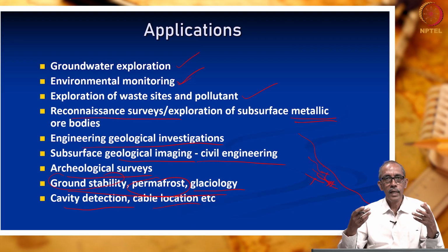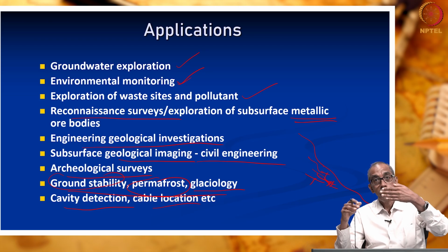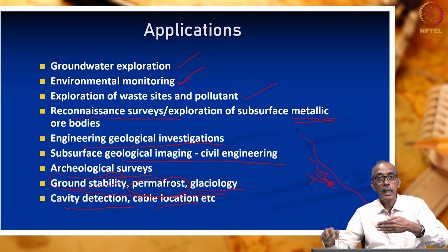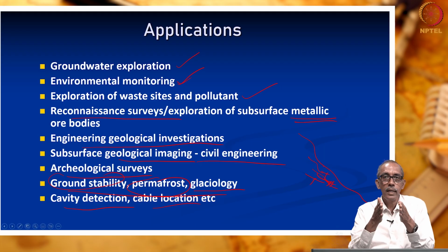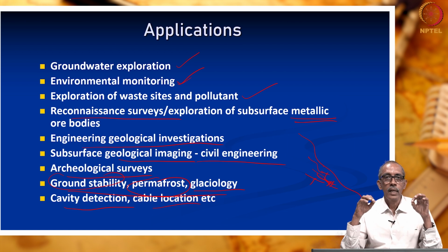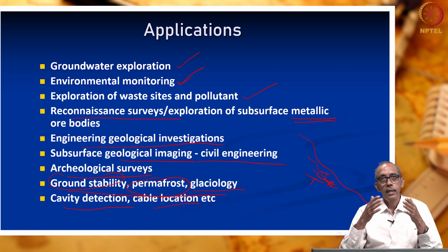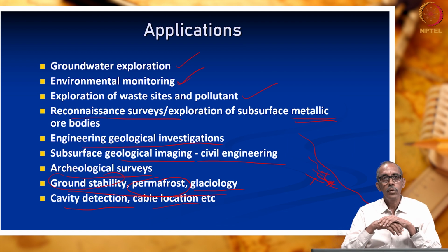Since we have done that, we are able to arrive at the vertical resistivity images. Not only along one profile, we can conduct the survey at several profiles. So, you are able to characterize the subsurface 3-dimensionally. And in this slide, we have looked into broad applications of electrical resistivity methods.